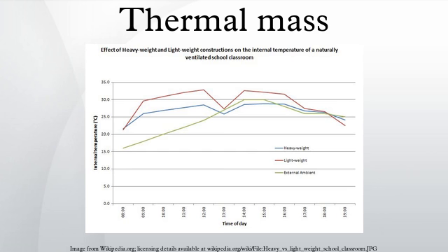However, this regeneration process is only effective if the building ventilation system is operated at night to carry away the heat from the slab. In naturally ventilated buildings it is normal to provide automated window openings to facilitate this process automatically. Hot, arid climates: this is a classical use of thermal mass.